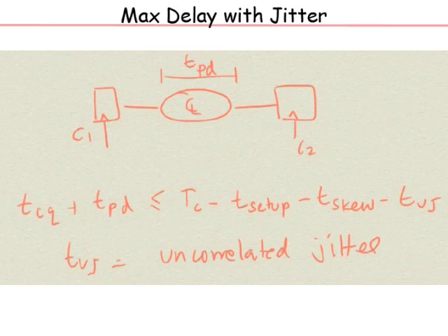At the end of the day, if you really look into it, there will be a noise component to the current, thermal noise, right? So you'll have some mean current and some small fluctuation in the current, and that fluctuation will change every time. That can be modeled, people have done a lot of work and they know what the thermal noise component is. So if you take such an oscillator, then the inherent noise of that can be characterized. Similarly, when it is locked to a reference, the noise is characterized, and so on.